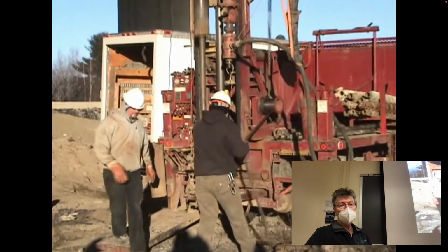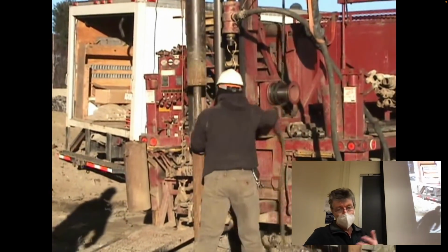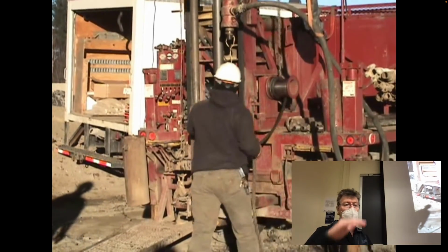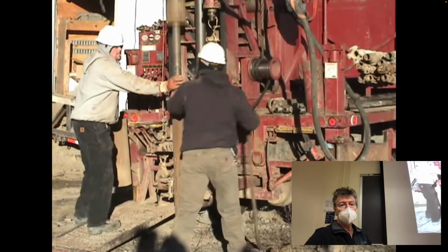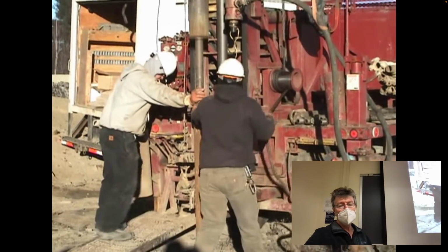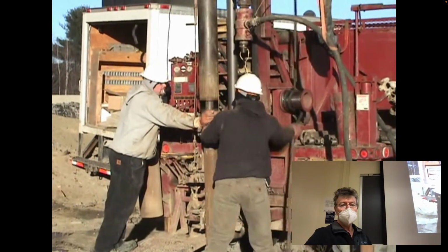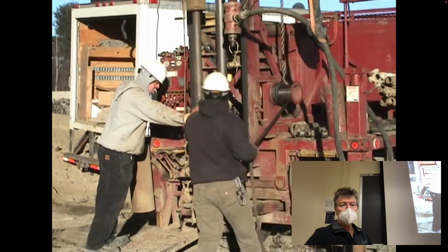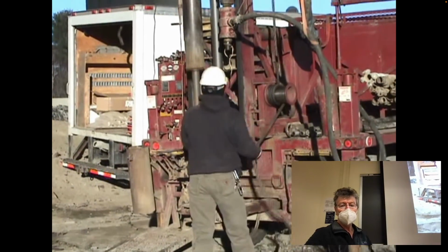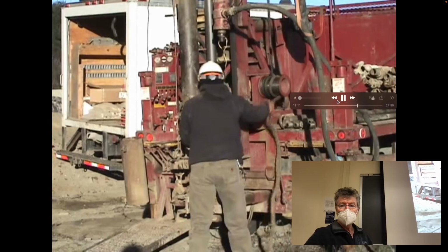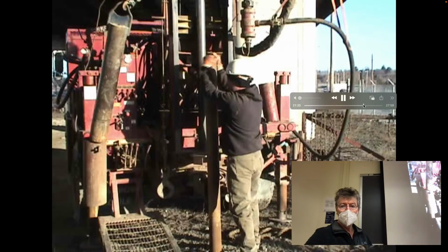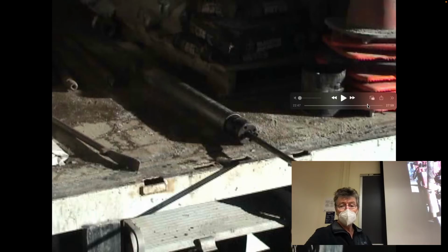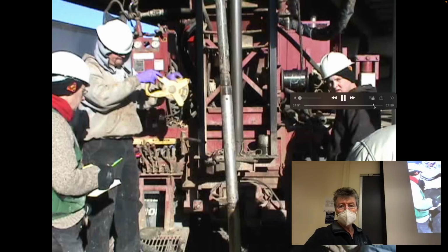So you're measuring the blow counts, 10, 11, 12, to be able to drive this a foot, and that gives you some impromptu measure of the strength of the material. And of course, after this, you're left with the drill hole to be able to do it as you wish. So I don't know if there's anything else in this or not. Yeah, you see it. So once you've seen this once and done it once, you know exactly how to do it. Piston sampler again.